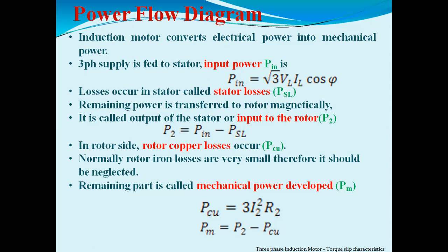So here also we are supposed to study the power equation, which we have seen in the DC motor. In the DC motor, what did we say? Mechanical power PM equal to what we have seen there, Eb into Ia. That is nothing but back EMF into armature current. So when we study the three-phase induction motor, you will get input power, that will be square root of 3 VL IL cos phi.